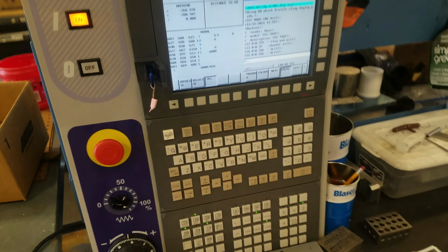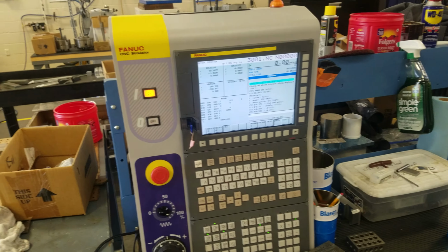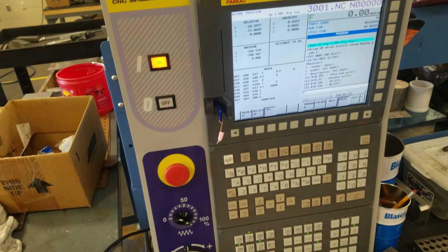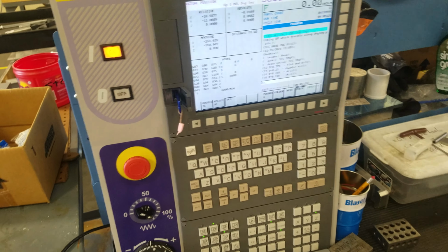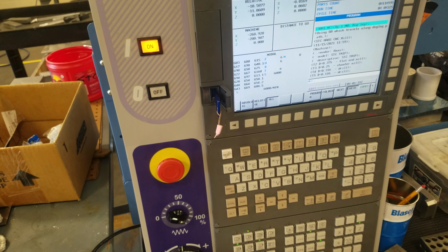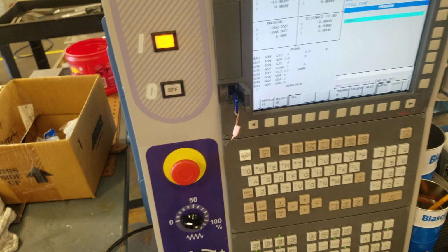Alright, this is part 3 on the Fanuc CNC control. I'm going to discuss how to do offsets. Now we're trained in here in Haas machines, so we have to do a couple more steps on the Fanuc control. If you need to load tools, we don't have an ATC tool change button. You actually have to program it through the MDI screen.